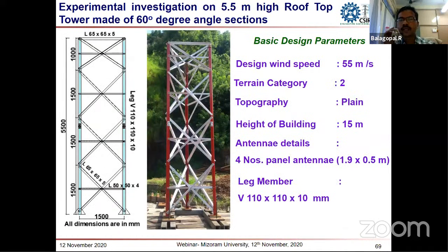And we have validated our buckling curve formulation on a triangular tower fabricated with the 60-degree angle sections. These are the design parameters we have assumed for our study.